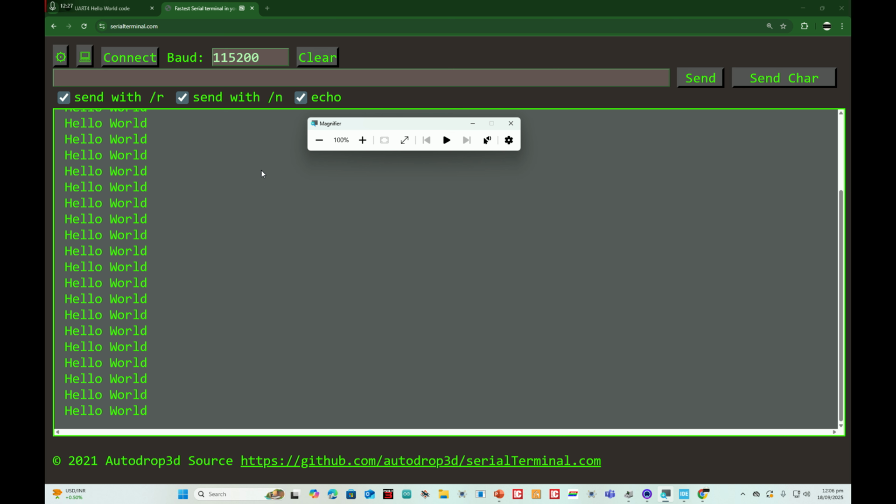If you are programming a complex project and you need a debugger or you need to see what is going on in the code, just like in the case of Arduino we have the serial monitor, here you can use an external serial monitor like this. So this is of great help. It can also be used to establish communication between multiple STM32s or with different types of microcontrollers like STM32 and Arduino, STM32 and PIC, or whatever you have.